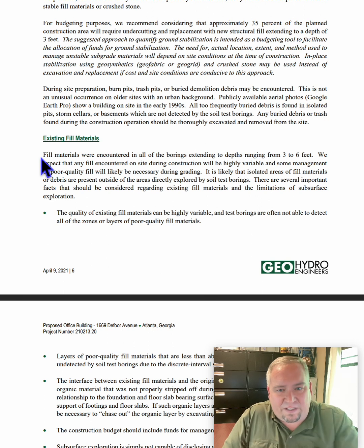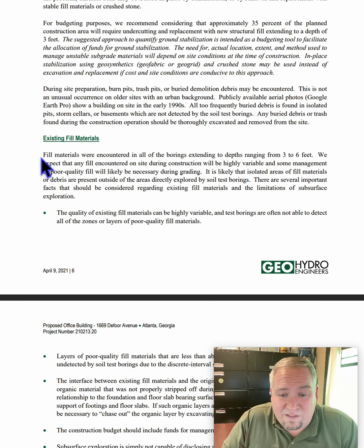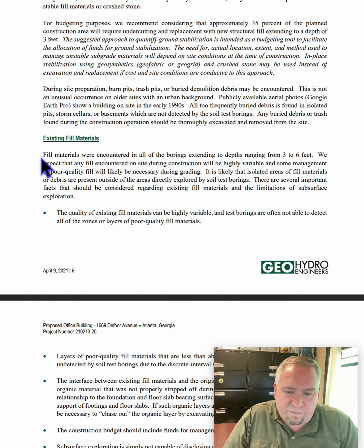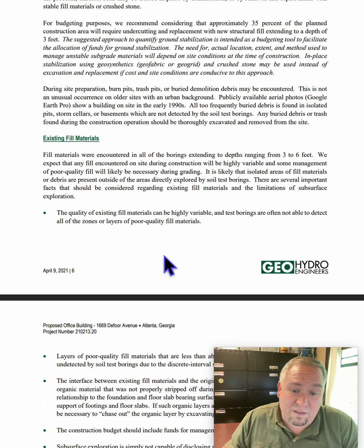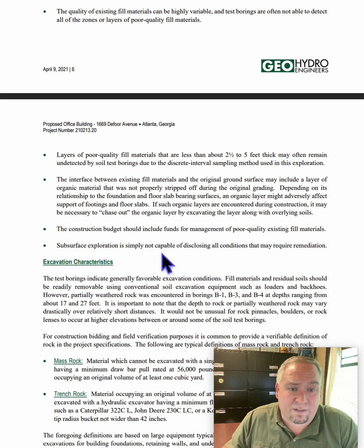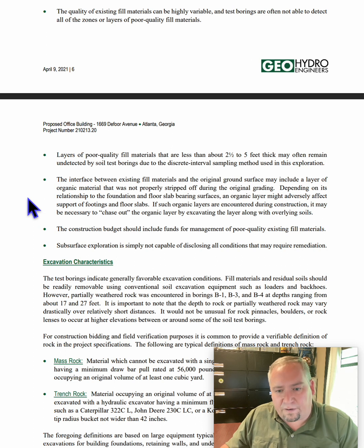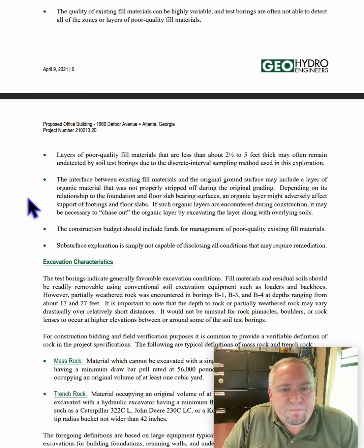So they're telling you, we've got 3 to 6 feet of this stuff. So I can already tell you, we've already prepped a customer reading through this that a lot of the soil is going to have to be removed, hauled off, or placed in some landscape areas outside the structural area. So we've tried to already put that in the budget so that when we hit this, we've already been aware of it, and we're trying to manage it and mitigate any further cost or downtime.